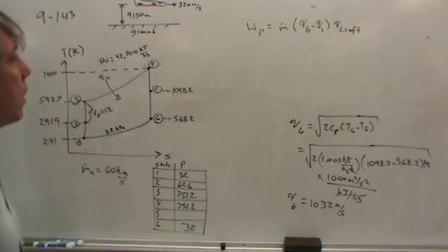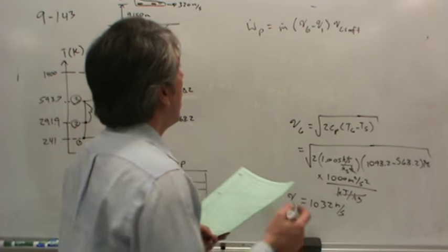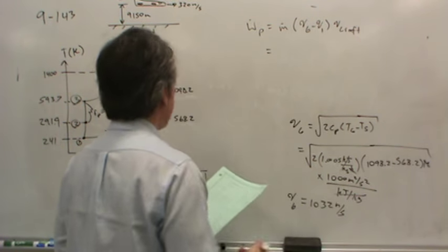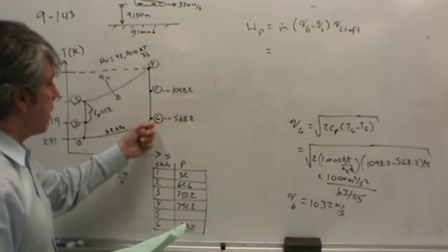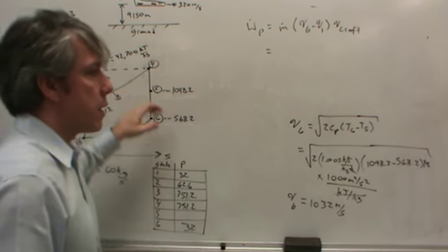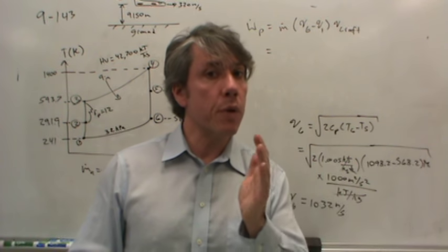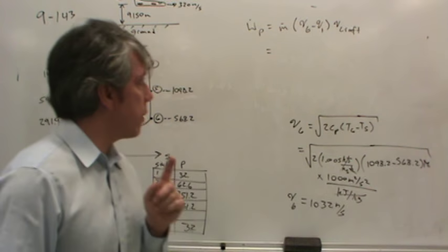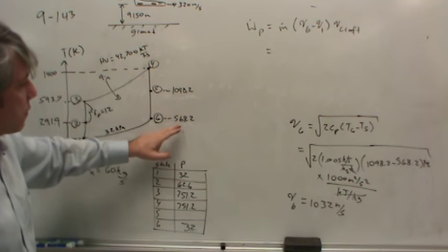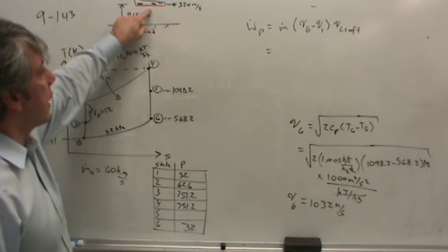All right. So if our reference frame is the aircraft itself, we know that the aircraft exit velocity we've calculated here is the exit. Now, let's think with me for a minute. We assumed that the kinetic energy coming into the nozzle was 0. What we're really saying is that that air was not moving with respect to the nozzle. So the reference frame we've selected so far for the nozzle is the moving aircraft. Therefore, this velocity that we've calculated, this 1,032 meters per second, is with respect to the aircraft.